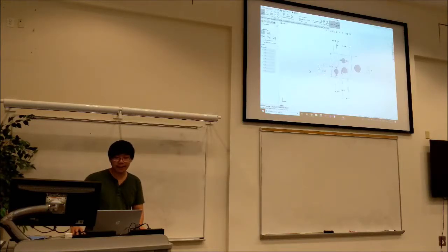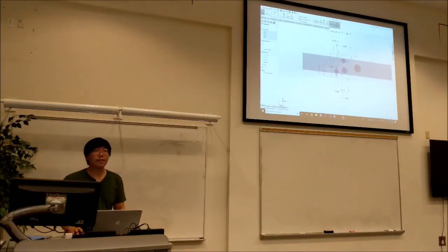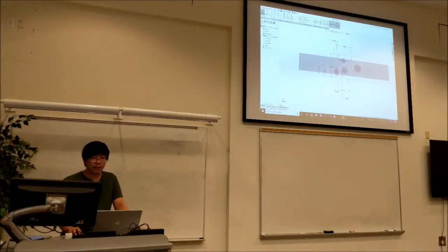So a way you can do that is to model the outside of the gearbox, and what it's connected to. In a lot of FRC robots, you have 2x1, right? So we can attach this gearbox to a 2x1. To plan out how we're going to mount it, we can just draw a rectangle that represents a 2x1. A 2x1 is 2 inches tall. And then we're going to make this centered on the gearbox.